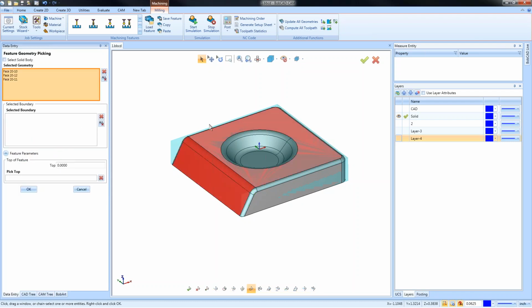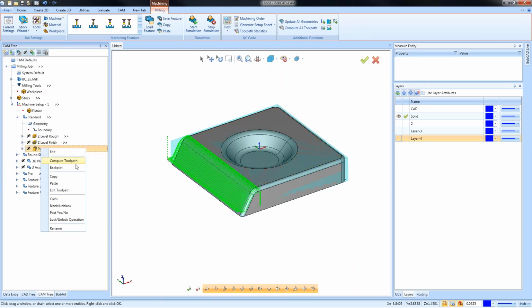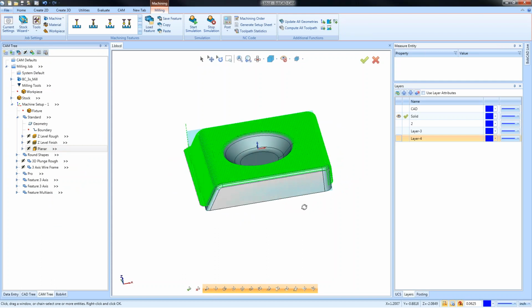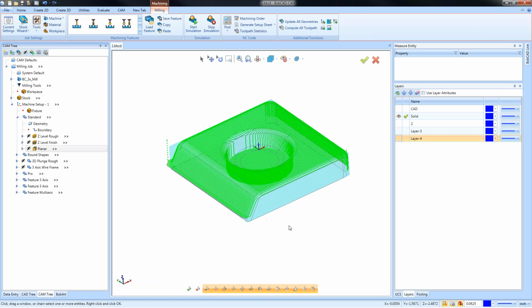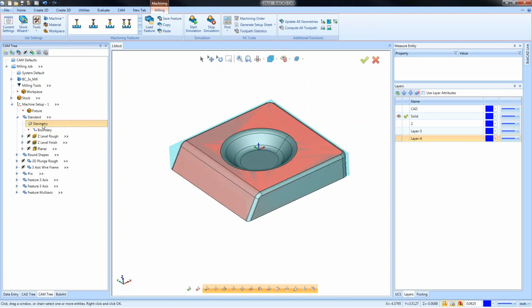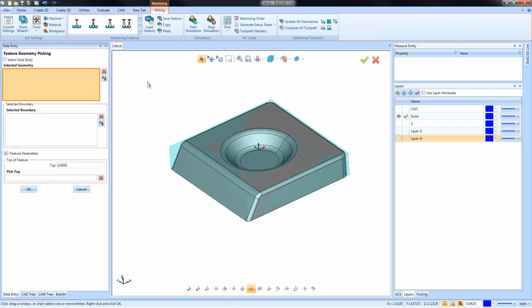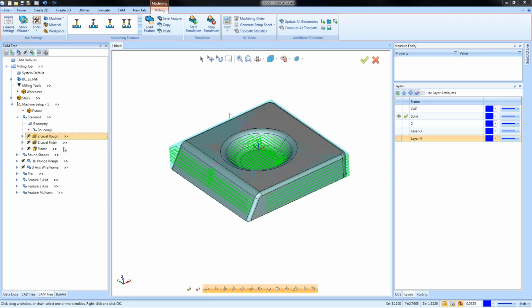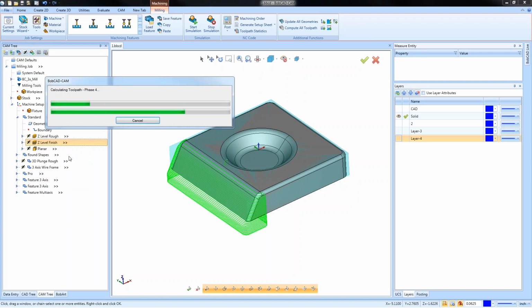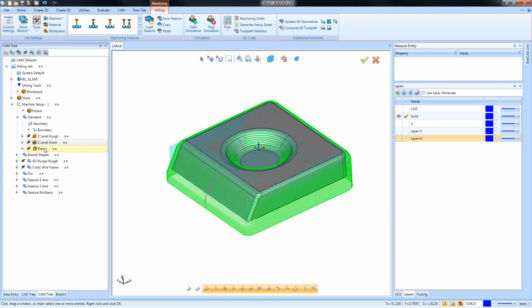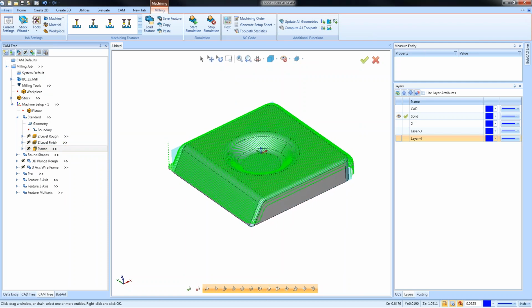If we add additional surfaces to our selection, and then we recompute, we can see how now whatever was selected is what is considered. And the toggle between the shading, I'm just hitting S on my keyboard to turn it on or off. So yes, what you select plays a big role. And again, I recommend for all new users to select all of their geometry as a starting point. Once you gain a better confidence and understanding of how to contain the toolpath and control it, then you can be a little more selective as far as what geometry you select.